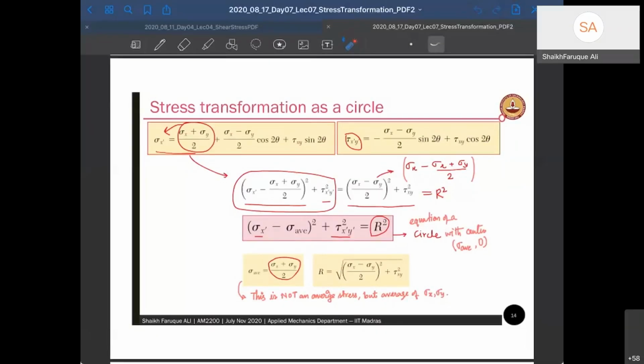So yeah, we left off in the last class, where we defined stress transformation for 2D planar bodies, right? We said there are three unknowns in a 2D planar body: sigma x, sigma y, and tau xy. So two normal stresses and one shear stress. The reason there is only one shear stress is that complementary shear stresses are the same, right? So we know the directions. Directions are defined; only the value you have to find out.